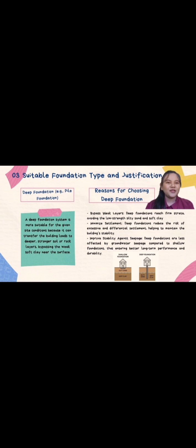Due to the previously mentioned issues, selecting the appropriate type of foundation is very important. Because of these ground conditions, deep foundations like pile foundations are more suitable. Deep foundations transfer the load to stronger soil or rock layers below the soft clay. This reduces the risk of settlement, avoids the weak upper layers, and performs better in wet soil. So, using a deep foundation is the safe choice to ensure the building remains stable and secure.